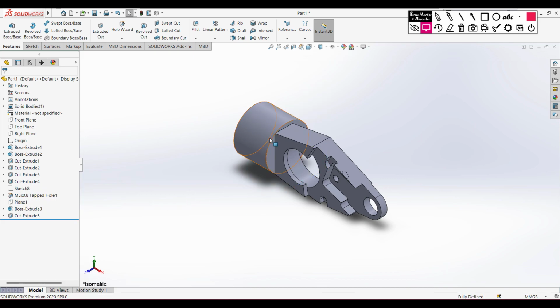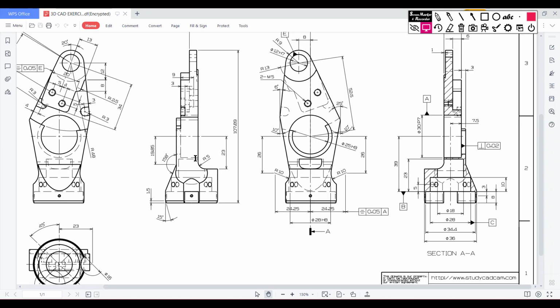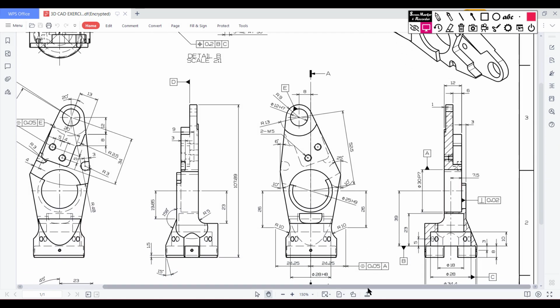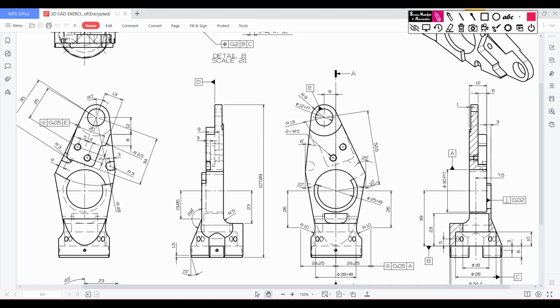Now we need to shape this lower portion, and how are we going to shape this lower portion? For shaping this lower portion, let's go to sketch. In our sketch we can see we have this circle. First of all, I'll draw this shape here. Okay, for drawing this shape, in our sketch we can see in here we have an angle cut. We have an angle cut of 158 degree. Okay, first of all, I will do this angle cut of 158 degree. Okay, so let me demonstrate.